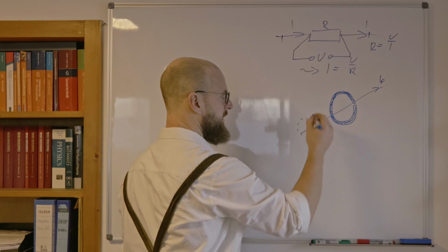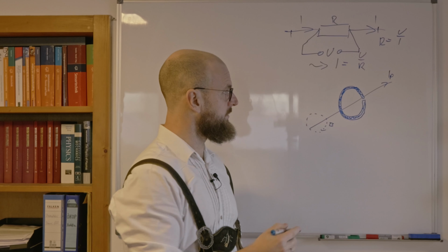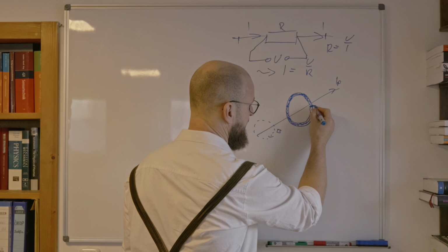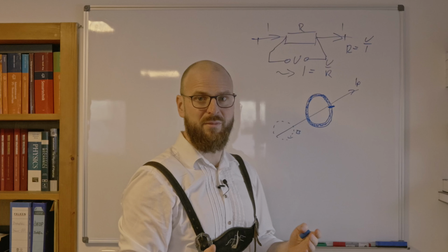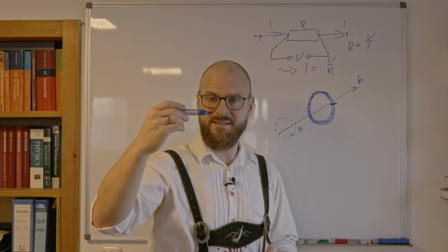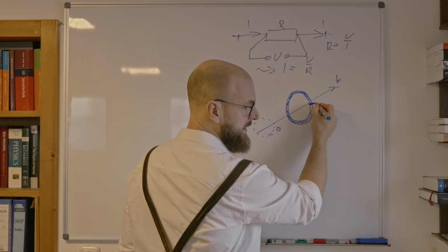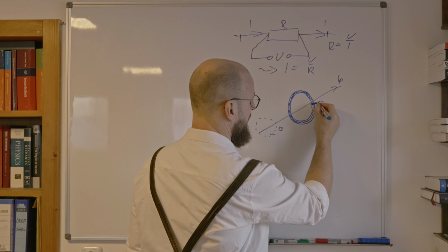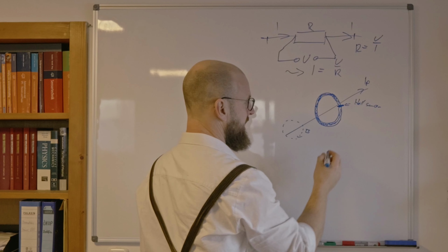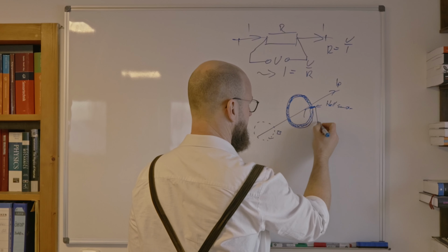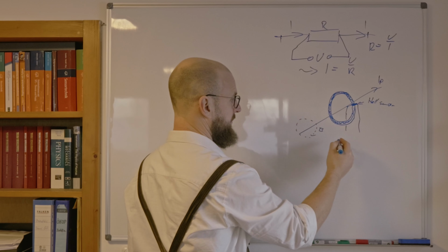So the magnetic field will align the atomic magnets in the iron ring, which then gives us very good access to the magnetic field at a certain radial distance to the wire, which we can then measure using a Hall voltage. So we have a Hall sensor over here. And now we can just use that voltage exerted over here, for example, to get a direct measurement of the magnetic field.